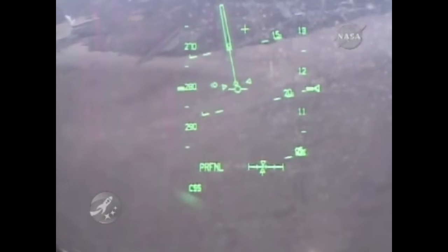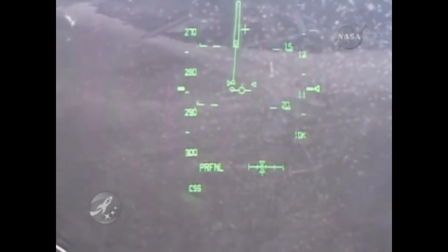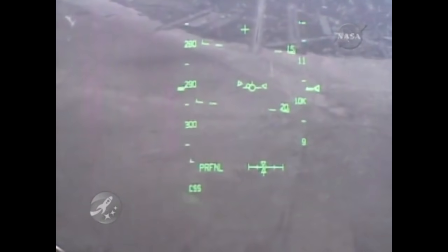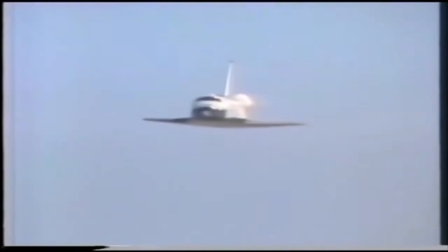It has no ability to perform powered flight in the atmosphere. Therefore, if the automatic landing were to fail, there is no doing a go-around. The shuttle would crash, be destroyed or sustain heavy damage, and the crew would be injured or most likely killed. Despite all of this risk, there was one flight that made an almost automatic landing. STS-3 allowed the program to perform lineup, final approach, and pre-flare maneuvers, and then the pilot would take over and complete the landing. Here was the result of that.